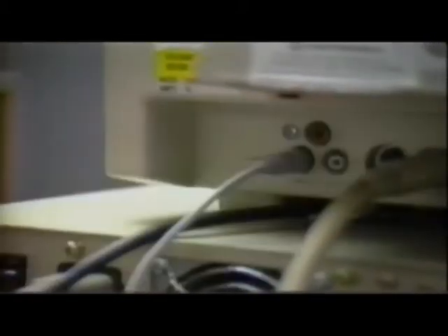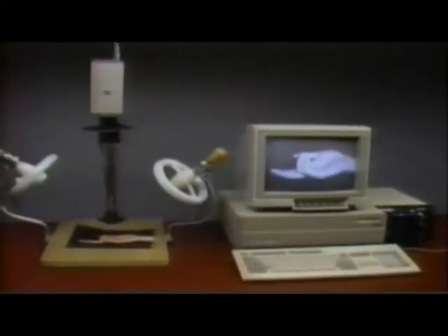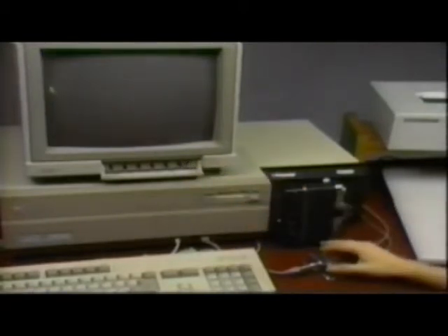Before digitizing, the camera must be focused. This can be accomplished by temporarily unplugging the camera's RCA cable from the DigiView interface and plugging it into the monitor's composite video input connector and pressing the CV-BS RGB button inside the monitor's front panel. The monitor now shows what the camera sees. After focusing, the RCA cable must be unplugged from the monitor and back into the DigiView, and the CV-BS RGB button reset to the RGB position.